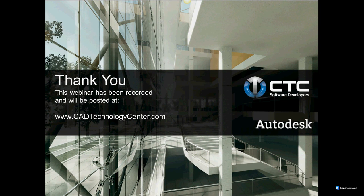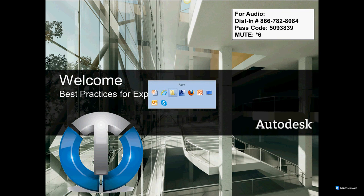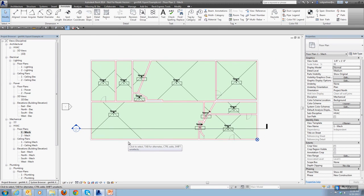So before we get on to the question and answer round, there are a few other pointers I wanted to mention. Now you can simplify the export process and make it easier for Revit to export gbXML files if you've got spaces that are going in a similar way. So ideally what you can do is you can have a separate sort of energy model that you will use to push out of Revit.